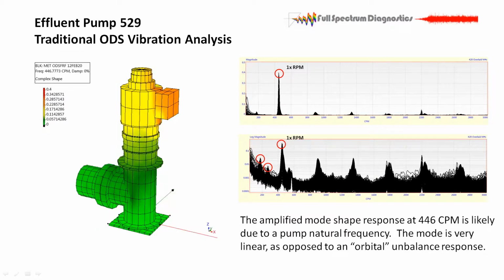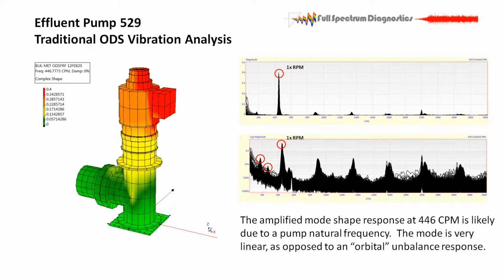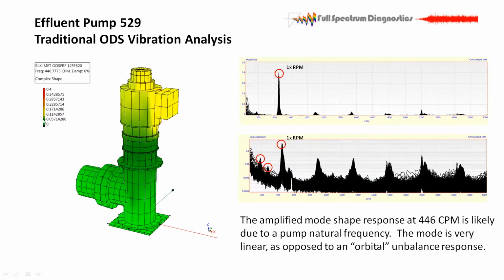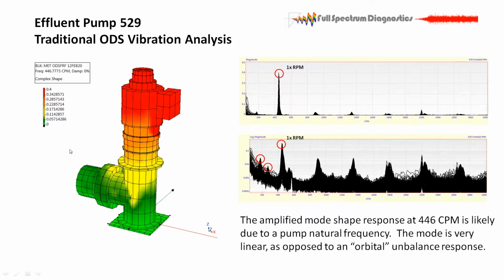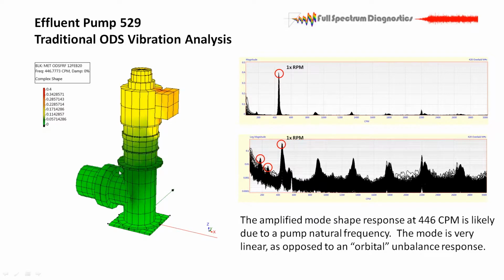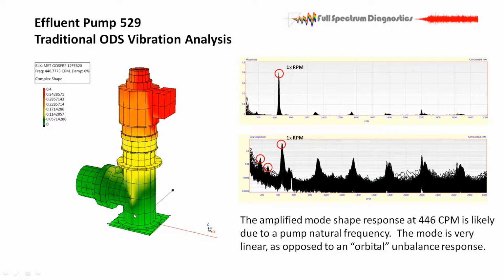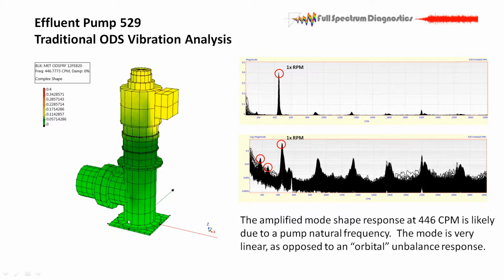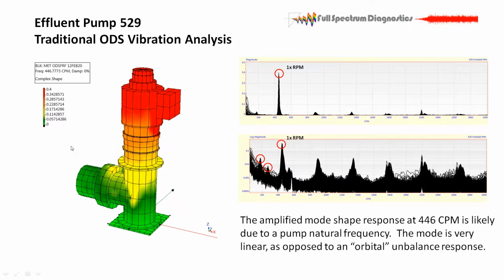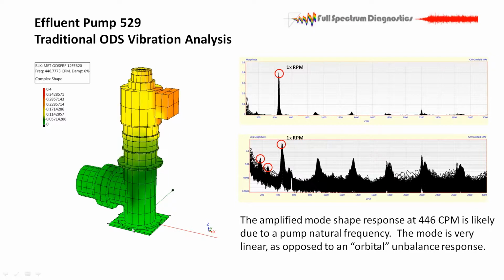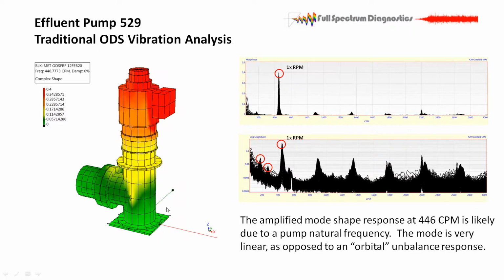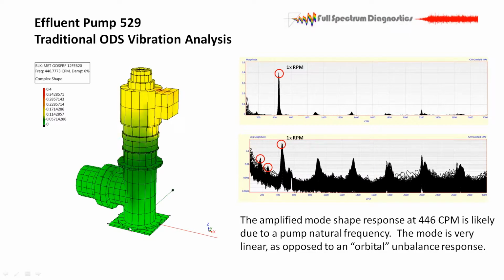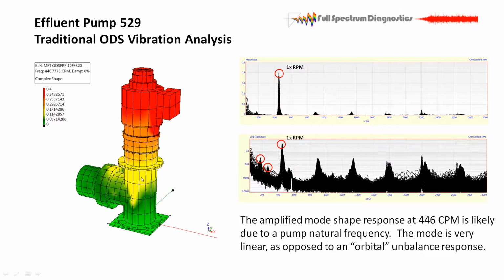This is that same image from another direction. And one other thing I wanted to mention, I'm still animating at 1 times RPM. My base, this darker green line is 0.057. So that is about where I'd start saying, hey, there's something wrong with the base, but it's above that level. So this lighter shade of green is below 0.057. So none of that is getting down to the actual bolted interfaces down here. So it's telling me the motion down here isn't causing all the vibration above.